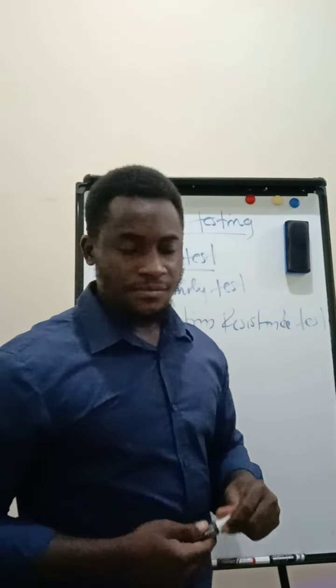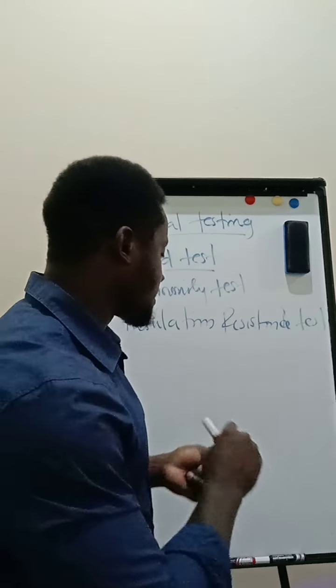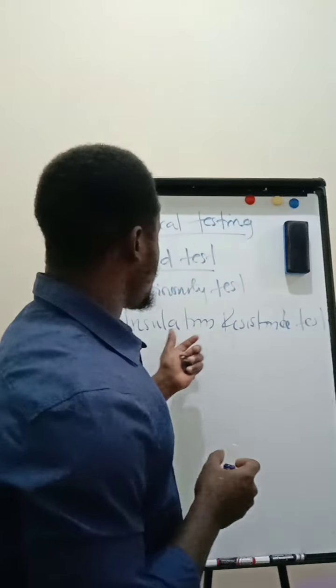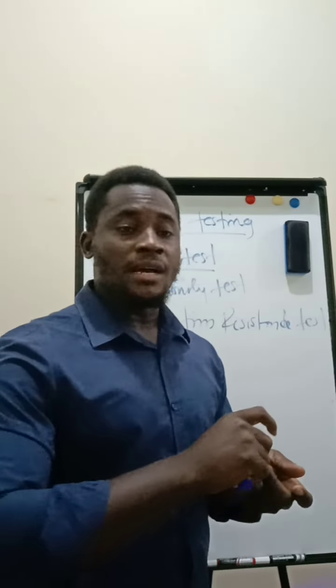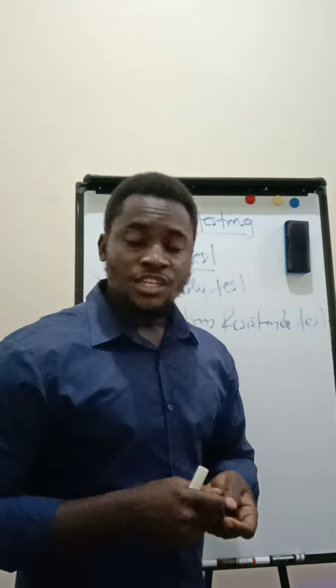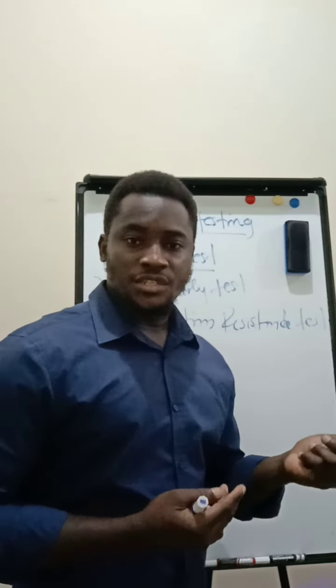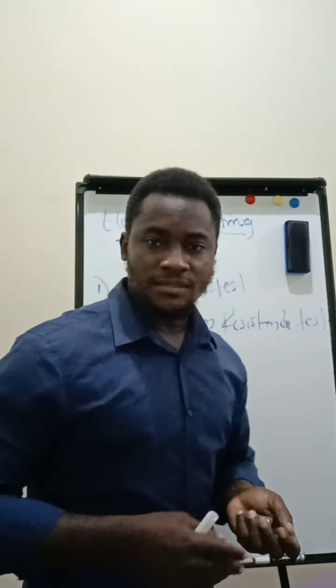So if you go through QCS 2014, it clearly states that when we are selecting our range for this test, we should ensure that the amount of voltage we are putting on the scale should be twice the nominal voltage of the supply or of the panel board which is under test.